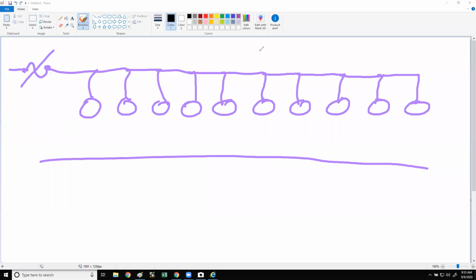Let me tell you what you do. Cut this thing in half, right? Turn this thing back on and see if you trip the breaker. If you do, you know the problem is in this half. You've just cut the whole field in half, right? If you don't trip the breaker, you know that the problem is in this half. Okay, so then what do you do? You cut it in half again, just like Brenna was saying.